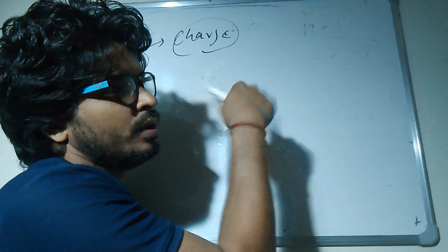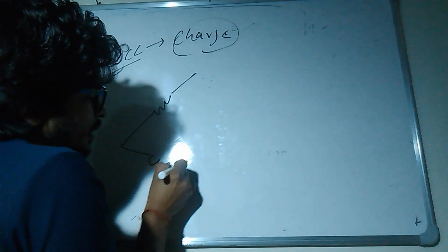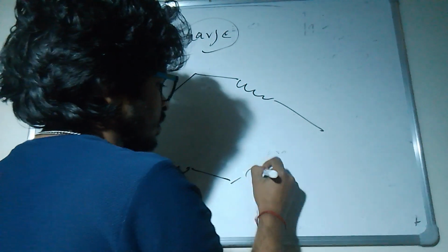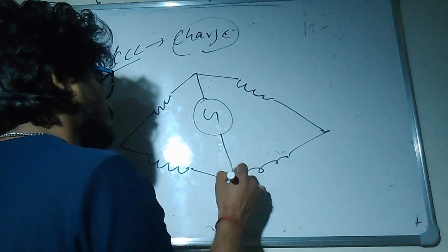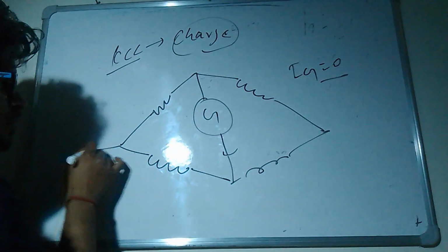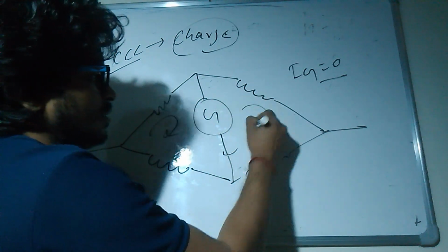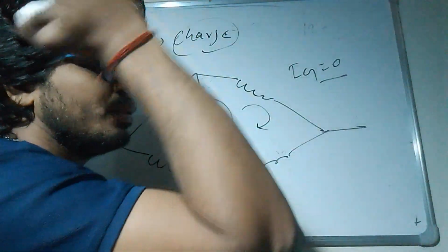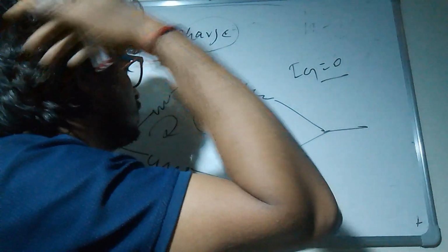During equivalent resistance we have already covered it. Now we are calculating equivalent resistance; there I already did the same thing. You have to arrange this circuit in such a way that the current through this is 0. So what is the rule for this? Ig should be 0. If you want to prove it, you can easily prove it by applying the loop law. Loop law is very important, and node analysis is very important. If you know node analysis and loop law, you are okay.